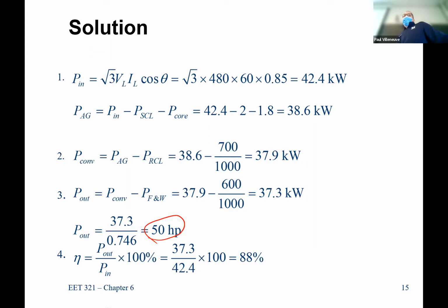They make cool noises. Well, I can put speakers on a car if you really need the noises, right? Yeah. Well, you can't cheat too, because if I have an electric vehicle, I also have to include the inefficiencies of charging the battery. I have an external charger that could be 90% efficient, plus whatever the losses in the converter are. So you're probably talking converter and everything efficiencies of 60 to 70%, which is still twice what it is for a reciprocating engine.